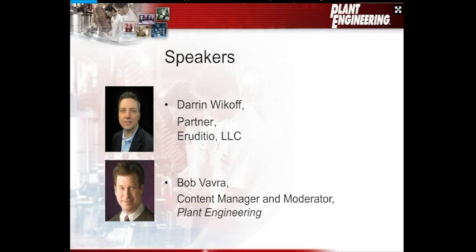As far as other predictive maintenance methods like vibration, lube oil, and thermography, those are great ways to reduce the demand on spare parts stocking. That's the way I interpret that question. If we're using motor circuit analysis, infrared, ultrasound, anything that helps us identify defects sooner reduces the demand on spare parts lead times. So I think predictive technologies are a great countermeasure, a great risk control to reduce those spares lead time risks.